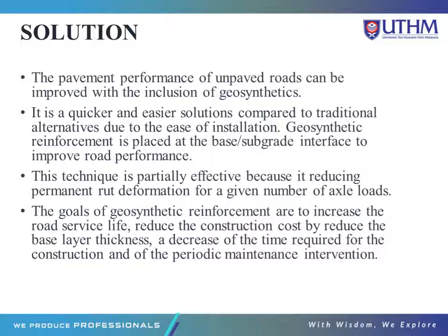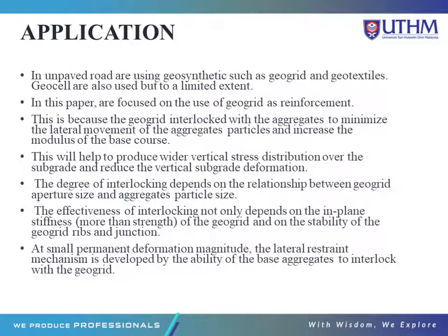The goals of the geosynthetic reinforcement are to increase the road service life, reduce the construction cost by reducing the base layer thickness, and decrease the time required for the construction and the periodic maintenance intervention. Okay, for the application. Normally, unpaved roads use geosynthetics such as geogrid and geotextile. Moreover, geocell is also used, but to a limited extent.